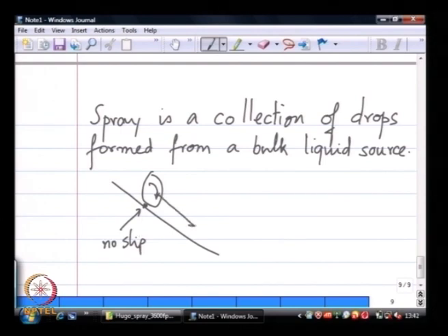Essentially that cylinder can only go up or down the inclined plane, it is a 1 degree of freedom system. A single point particle in air can move in 3 different spatial directions, it is 3 degrees of freedom. So, if I tell you the position and velocity of a particle in space, that is I have to give you 6 numbers, I have told you everything there is to know about the present condition of this particle.